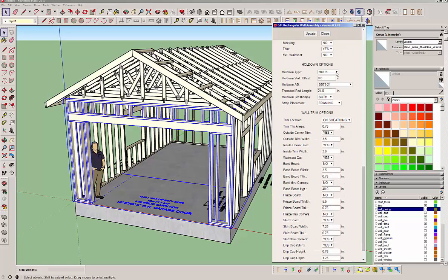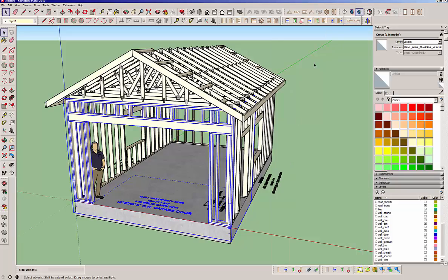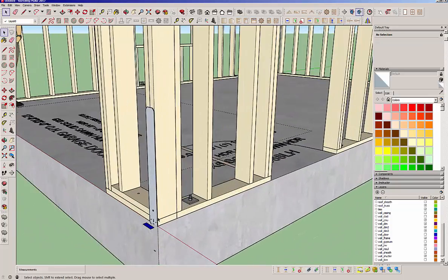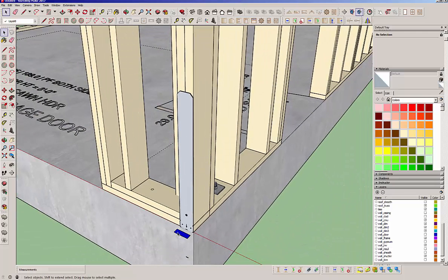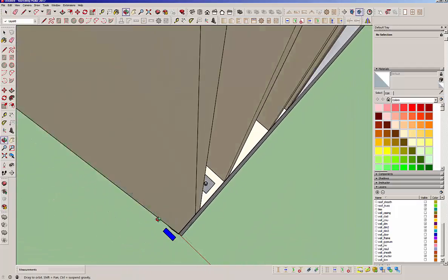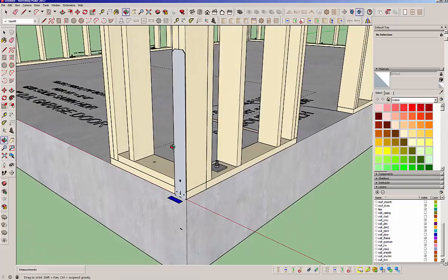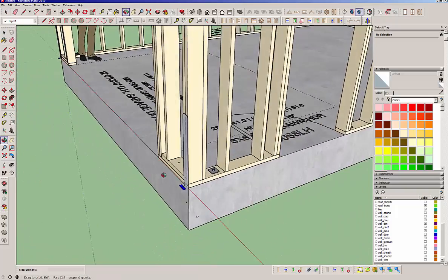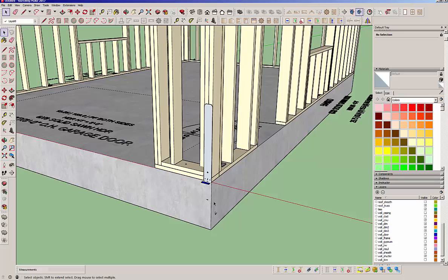and we're going to use just a regular STHD14, both sides, yes, and we don't need hold down bolts, so let's hit none there and hit update. Okay, and now you can see that we've got a strap hold down right there on each corner. Close that out. I'm just going to zoom in right quick here and show you. And you'll see also that you have this little representation here just showing you there's a hold down there in the structure. When you're in plan view, you'll be able to see that. But there's a typical strap hold down that's embedded into the concrete of the structure.